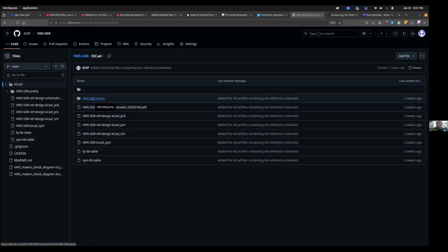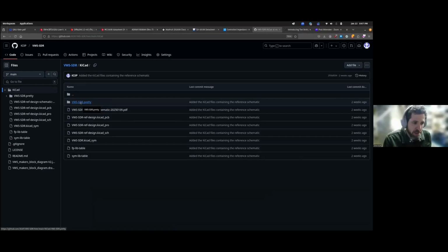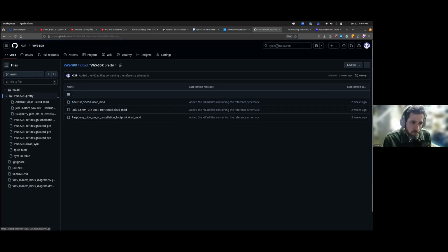So these are what the component, the pads and the silk screen would look like on a PCB. We have 3 custom footprints in this board, each one in its own file in that folder. I'll show you briefly how to import that now, but just so you know that they're available and you'll be able to use them and you won't have to redraw them yourself.